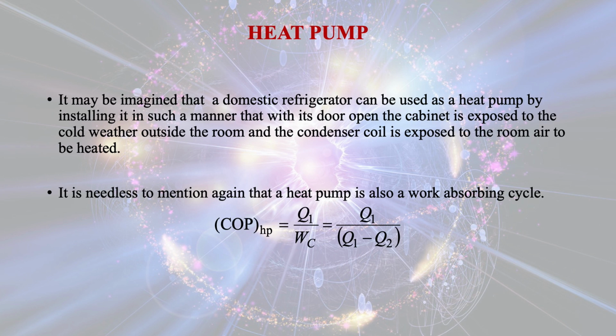So the coefficient of performance of a heat pump is equal to Q1 divided by WC. We can also write this as Q1 divided by Q1 minus Q2. If you do a little algebra, you will find that the coefficient of performance of a heat pump is equal to 1 plus the coefficient of performance of a refrigerator.